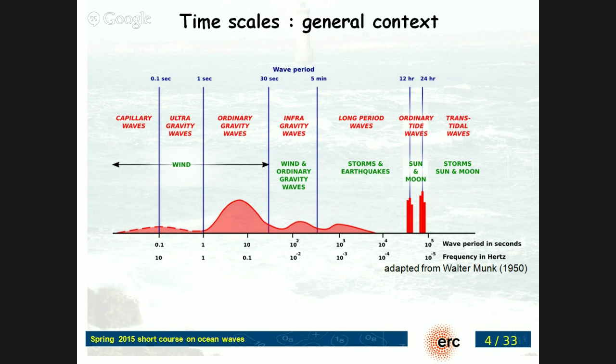And so people that work on these waves either use spectral models with the bispectrum on top of the spectrum, or they use phase-resolving models. Yet, what we've done in the code, as part of the version that you'll be using, we've developed some parameterization to generate the free infragravity waves from the ordinary waves. And so we have some source term for that.